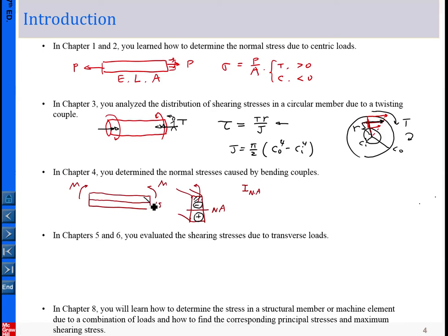For this example, the bending stress is in linear distribution. Okay, and the magnitude of the bending stress is basically equal to My over I, and I is the one we've calculated here, and M is the bending moment, which is given or determined. So what is y? y is this. So again, if you're interested in knowing the bending stress at this level here, you simply measure the distance from the level to the neutral surface, we call that y.